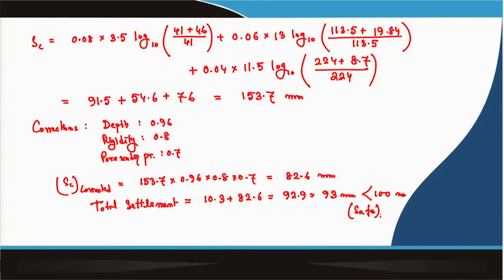So you can model a beam under plane strain condition for a strip footing, when the beam has infinite width, and you can also model a beam with finite width. In those cases you can use the beam on elastic foundation concept, and you can use it for your railway track, for combined foundations, for strip footing, for railway track.